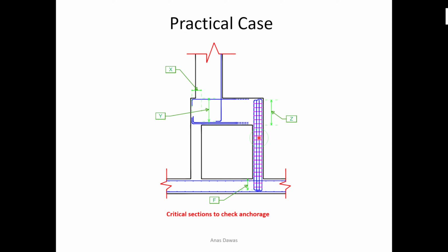Also, the reinforcement bars for the column should be developed inside the beam, using a straight bar development length or 90-degree development length. Also, we have to check the anchorage requirement for the dowels of the supporting columns inside the footing. We have to see that the depth of the footing is enough to develop the bars in tension and in compression. And we have an additional check here: the lap splice, by the way, but I will not talk about this in this lecture.